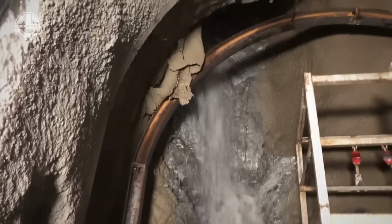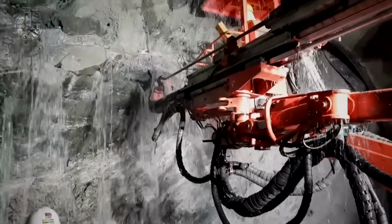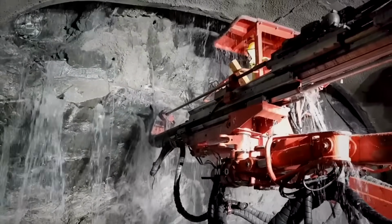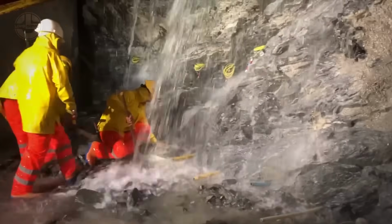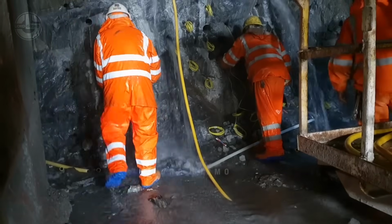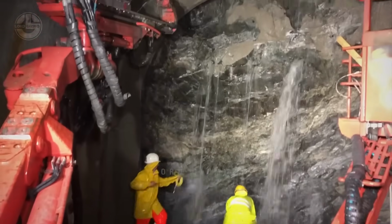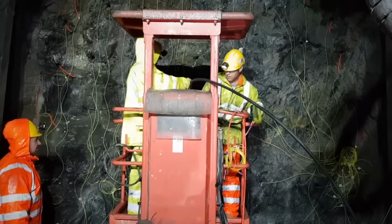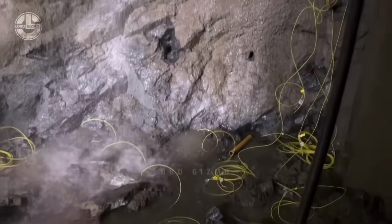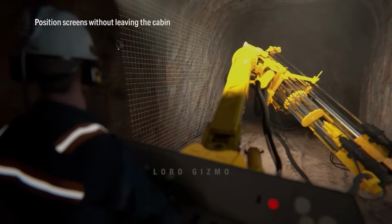It's important to understand these issues to appreciate the intricacies of underground mining. In underground mining, ground control refers to managing risks associated with the stability of the rock and soil surrounding the mine tunnels. One major risk is rock bursts, which occur when rocks suddenly fracture and burst due to stress caused by intense pressure at deep levels. It is classified as an artificially induced disaster by mining excavations. This happens through the process of energy accumulation, where energy is evolving and an abrupt release is happening.